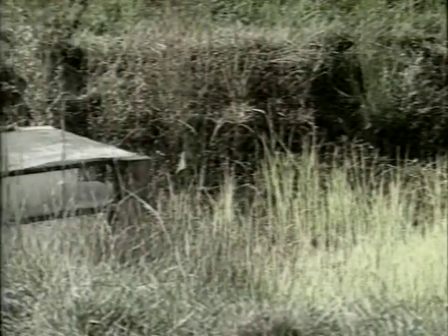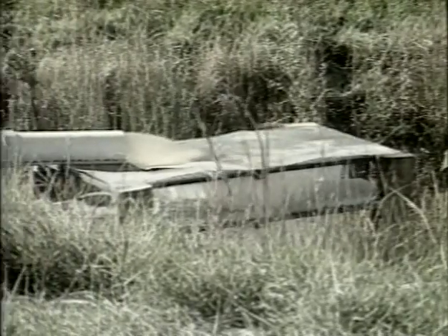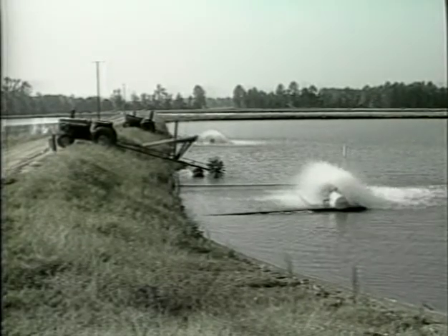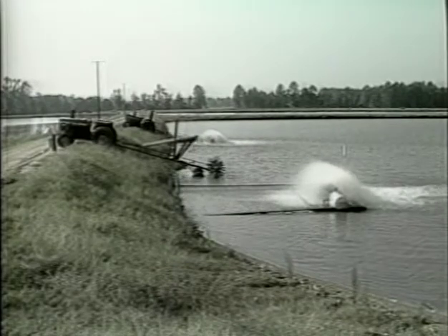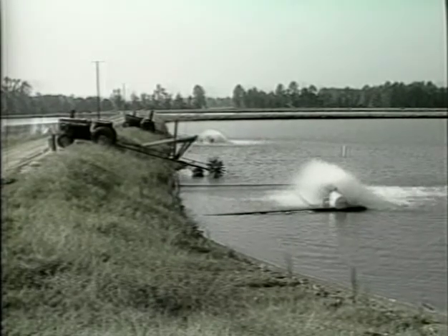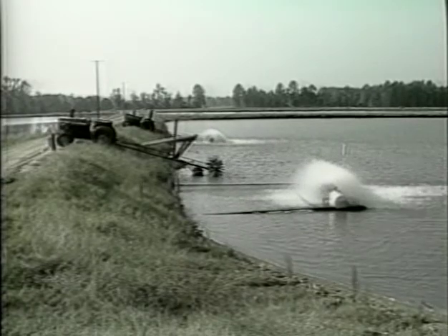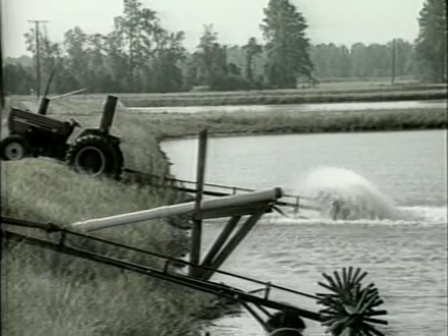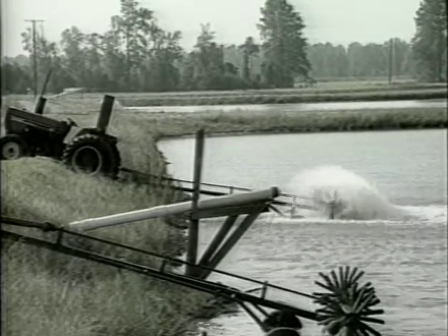Pumping water into the pond seldom helps raise oxygen levels unless the water is pumped over a splash device or sprayed out over the pond, thereby allowing oxygen to diffuse into the water. This is because most well water is nearly devoid of dissolved oxygen. If possible, it is best to utilize aeration devices. As mentioned, there are many models to choose from. Consult your county agent or aquaculture specialist for assistance in making your decision. There is also information available on oxygen transfer coefficients for various types of aerators in most state extension offices.